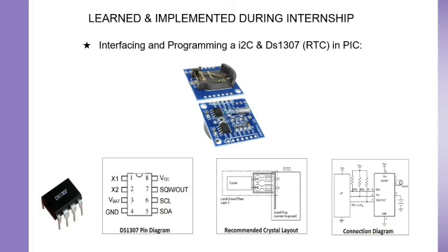Some microcontrollers like LPC2148, LPC1768, etc. have on-chip RTC, but other microcontrollers like PIC16 or 32 do not have on-chip RTC, so we should use an external RTC chip. There are different types of ICs used for RTC like DS1307, DS12C887, etc. In this slide, we will see DS1307.